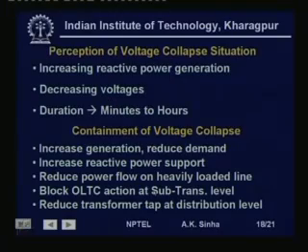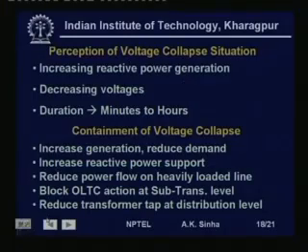So, this is not a blackout, but since the voltage has got reduced, if you have incandescent bulbs, they will not be glowing at their full, they will provide much less illumination, and that is why we call that situation a brownout situation. So, we sometimes take help of brownouts to avert blackouts in the system.